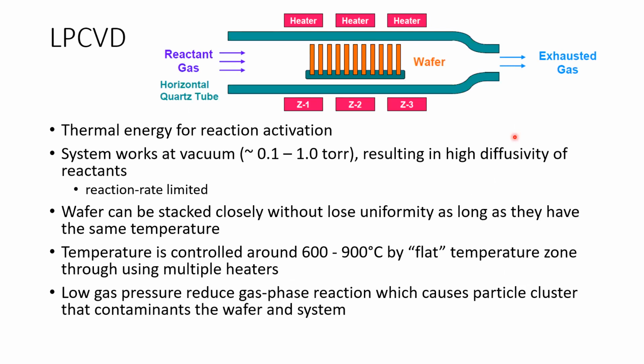For LPCVD, thermal energy is used for reaction activation. Because the system works at vacuum, 0.1 to 1 torr, it's very low pressure, the diffusivity of the reactant can be very high. So the process is reaction rate limited.